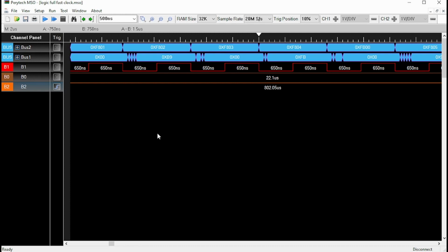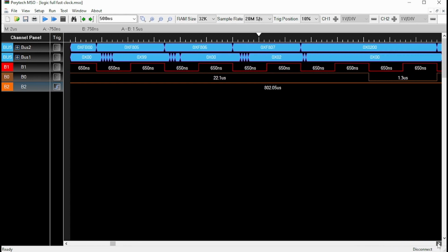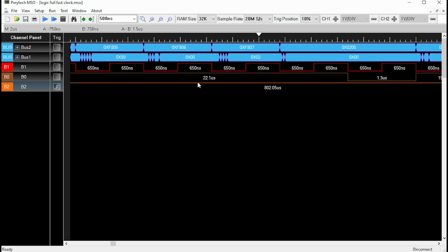And it goes back to what we saw before about that line which you can't really go below. And I think if you look at this, we're seeing here, this is around 650 nanoseconds. So this period here you could say would be around 250 maybe maximum. So after 250 you've always got some valid data on that data bus. And that's pretty much all we need. So that's why this circuit is working just fine. But we do see that it's not as stable as we'd otherwise seen before.